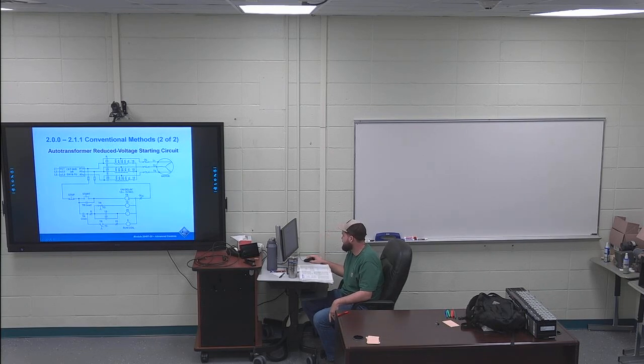So if I go to TR, I can go and look where my 2 sets of contacts are. So TR will close here, and TR will close here, giving power to the bottom half of this control circuit, and then also sealing around my start push button. One set of closed instantaneous contacts provides holding for the timer.